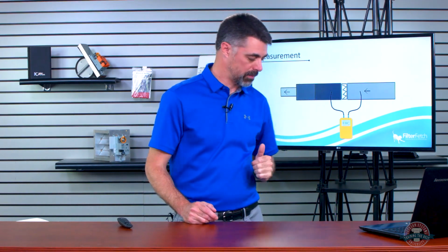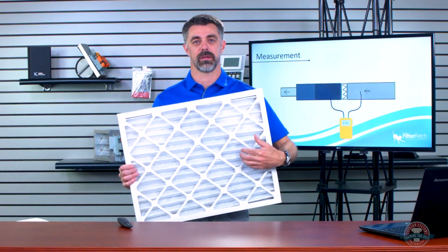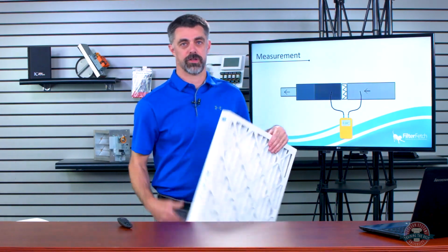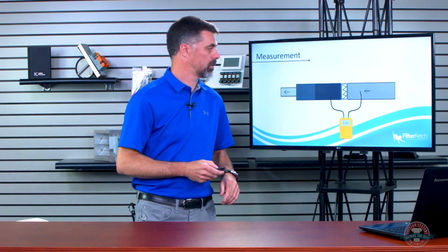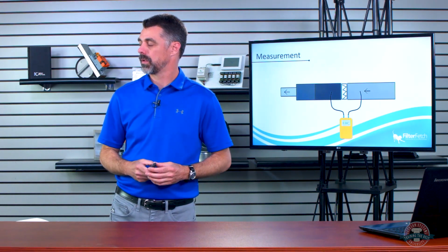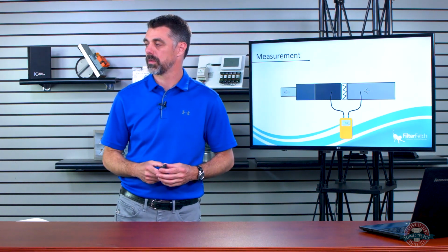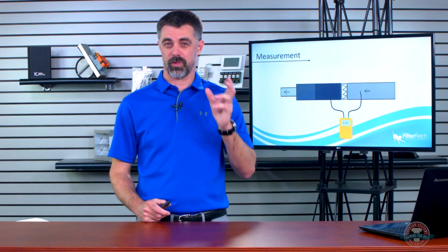Whereas if we're talking about a pleated style or a media filter, something with a media in it, this actually gets more efficient as it gathers dirt and catches more, because the holes get a little bit smaller. And another question from Ferris: do the pleated air filters or any other filters create any air turbulence? They can create some air turbulence, but I find a lot of them tend to straighten it out a little bit.